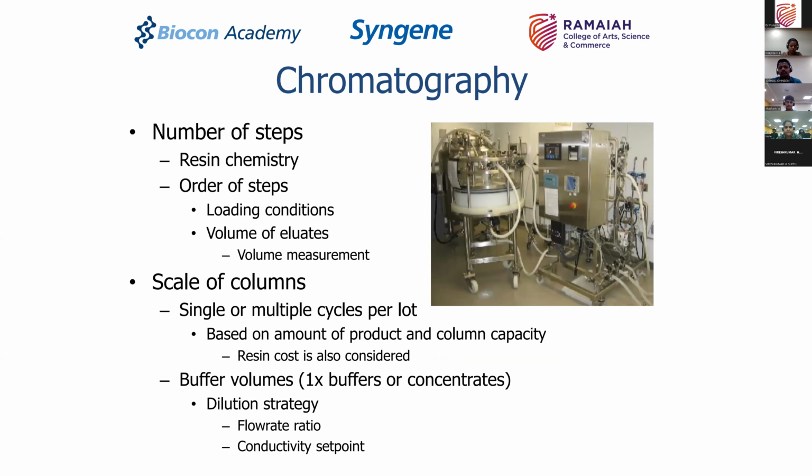The chromatography, there is a number of steps involved. You need to decide the kind of resin which will be used for chromatographic separation. And then what are the steps involved in chromatography? What are the loading conditions? What is the flow rate at which you are going to send the liquid into it? At what pH? At what conditions of temperature are you going to send it? Because what is happening in chromatography is that there is an affinity which is happening, or an ion exchange which is happening, and in both cases you need to determine the right conditions at which the affinity or the loading or the ion exchange will happen.